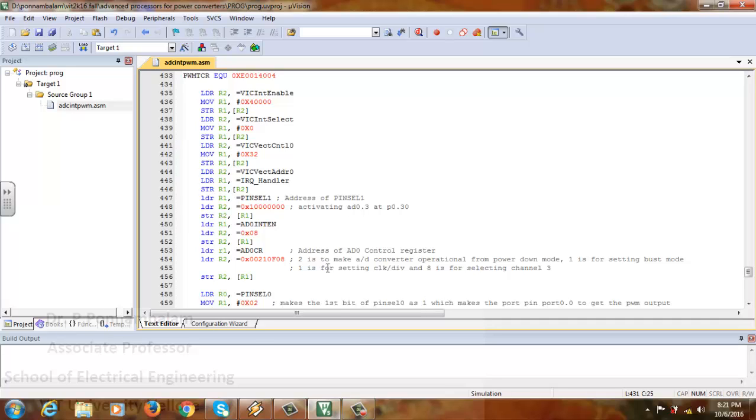But as far as the hardware board is concerned, if we give it as 1, it's not functioning. So I'll be giving the maximum value, so the frequency is reduced so much that the analog to digital converter is capable of accepting the analog value and converting it into its equivalent digital value without any problem. For that reason, we need to make this change of F08.